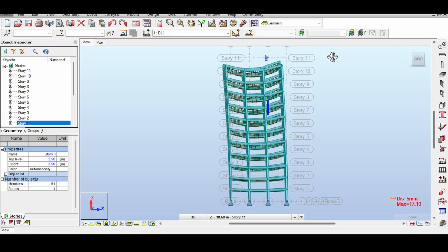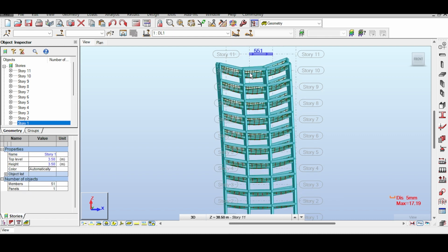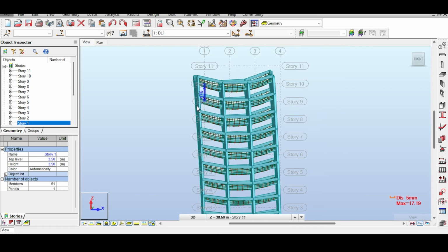But I said something, and I want to further qualify that, because I know some of you are finite element method nerds, so I need to be a little bit careful here. It is not only the vertical stiffness that causes the leaning, it is also the interconnection, the rigid joint that makes the structure lean. What I'm saying is, the reason why the structure is leaning is not only because the left side columns are weak, it's also because the beams and the left side columns are connected via rigid joints. Because otherwise, the entire structure would not lean, but the plates would be inclined.